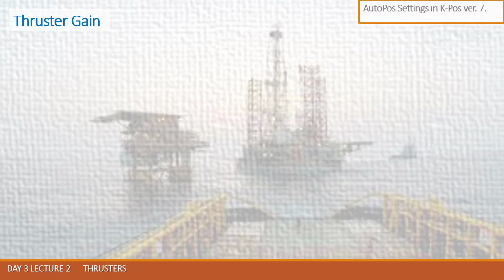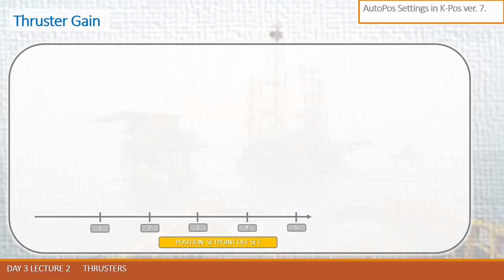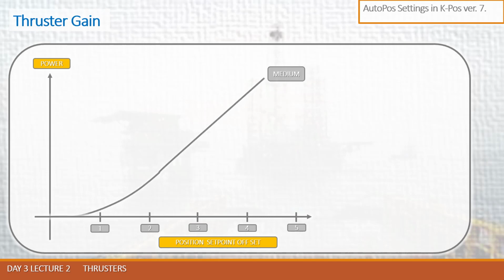Also, gents, you have to keep in your knowledge luggage the next information. Gain can be changed for both joystick and auto control modes. In a normal situation, when you are in joystick mode, we stated already that you use it as reduced, but also it can be increased to joystick full thrust, and there is even a special button on the panel to increase thrust in one click.